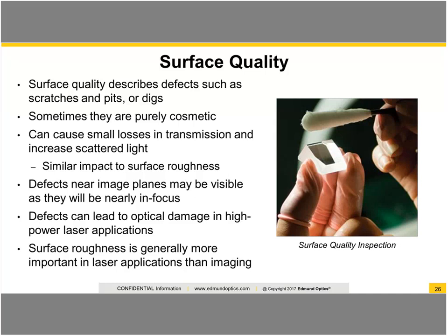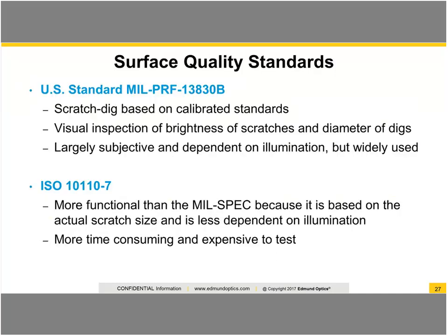Another time is in high-power laser applications. Defects often lead to the presence of optical damage when they're exposed to very high fluences in laser applications. And so that's another time that you might want to specify a much tighter tolerance or much higher quality on your surface. Surface roughness is also generally more important in these laser applications than it is in an imaging application. So that's something to keep in mind as well.